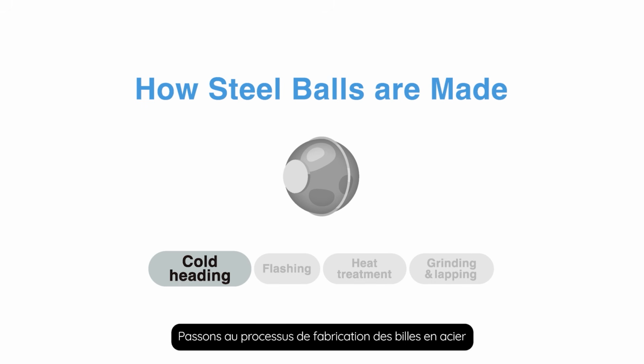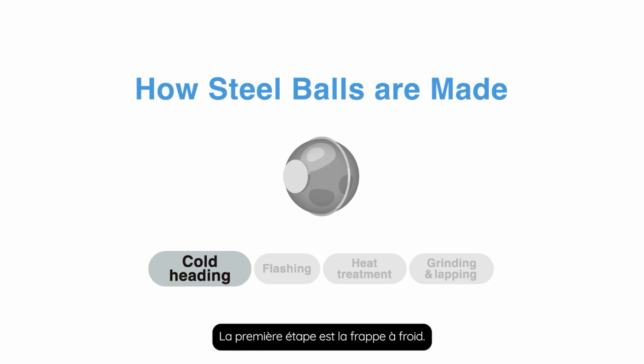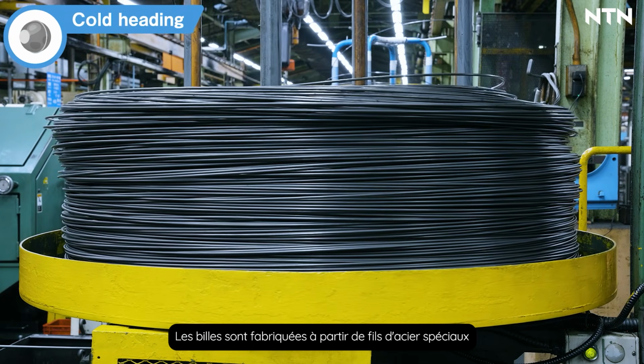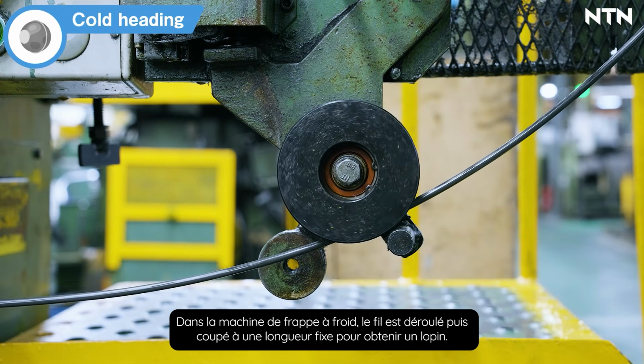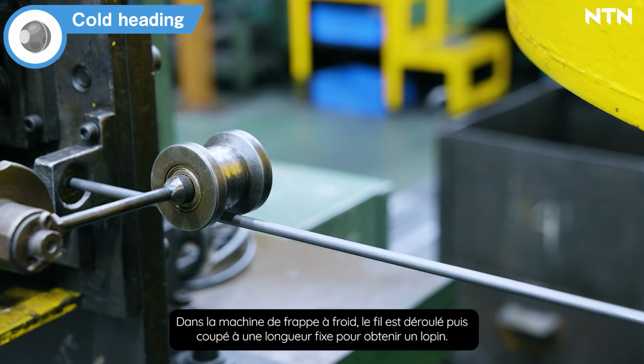Now that the outer and inner rings are complete, let's move on to the steel ball manufacturing process. First is cold heading. Steel balls are made from bearing steel wire material. In the cold heading machine, the wire is cold drawn and then cut to a fixed length.